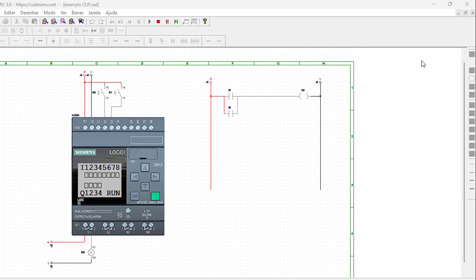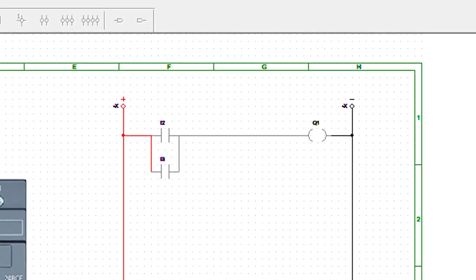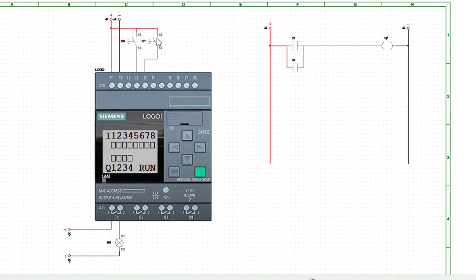In a simple application with the PLC, note that we have the same connection of the 2 buttons at inputs I2 and I3 of the PLC, in addition to the lamp at output Q1, similar to the example of the AND function. Note that to execute the logic of the OR function, a program was developed in ladder language with 2 open contacts with addresses I2 and I3 in parallel, similar to the electrical circuit. When the buttons are not being activated, the Q1 output is equal to 0; in any other combination the Q1 output is equal to 1.